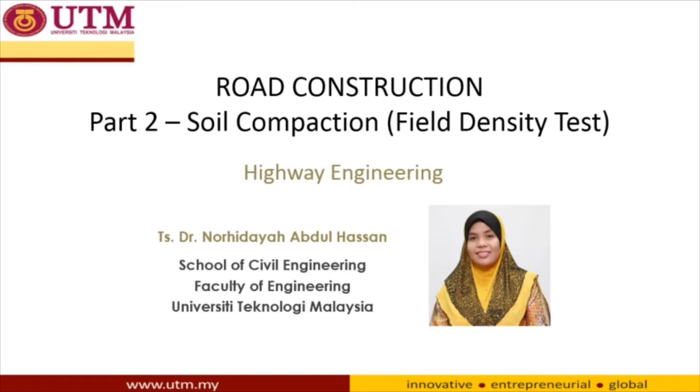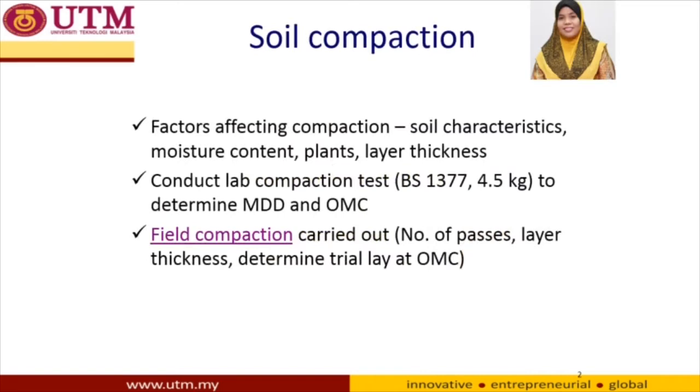In this video, I will continue my discussion on road construction, focusing on field density tests. In this lecture, we will discuss soil compaction, particularly for the layers of the subgrade, subbase, and road base, or to be exact, for the unbound granular materials. Basically, soil compaction on site depends on a few factors, including soil characteristic, moisture content, machineries, and layer thickness.